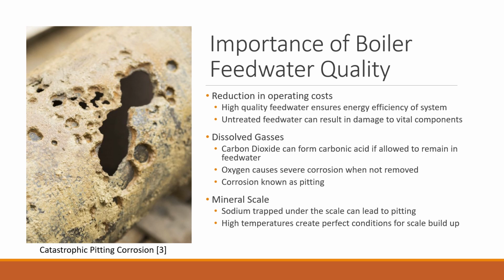One of the big concerns with untreated feedwater is dissolved gases. Carbon dioxide and oxygen are the biggest concern with the dissolved gases, as carbon dioxide can form carbonic acid if allowed to remain in the feedwater, and oxygen by itself causes severe corrosion when not removed. This corrosion is known as pitting, and you can see an example of this to the left. This is a catastrophic failure due to pitting, and ideally you never want your system to reach this point.